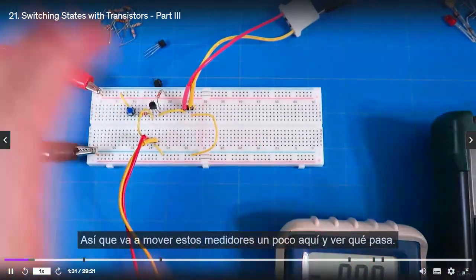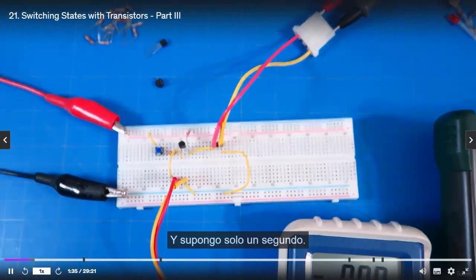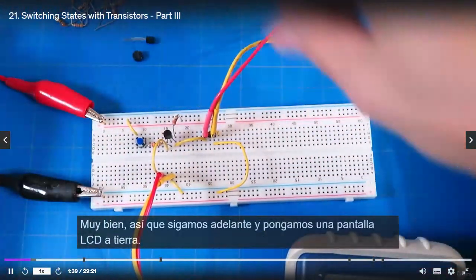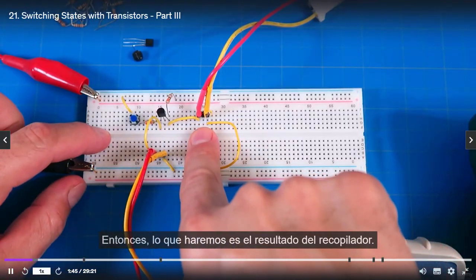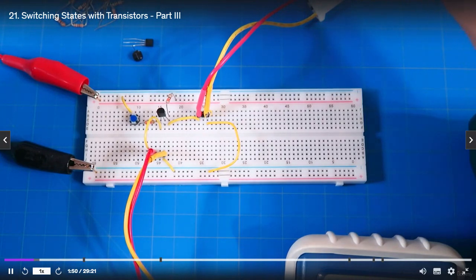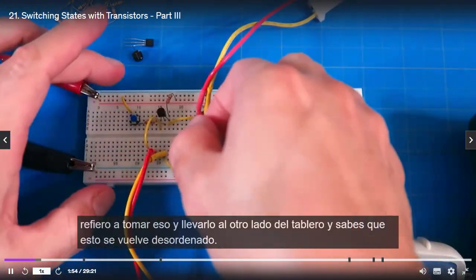I'm just going to move these meters a little bit here so you can see what's going on, and I'm going to zoom in. There we go. All right, so let's put an LED to ground. Here's the output of the collector. I'm going to take that and bring it to the other side of the solderless breadboard.